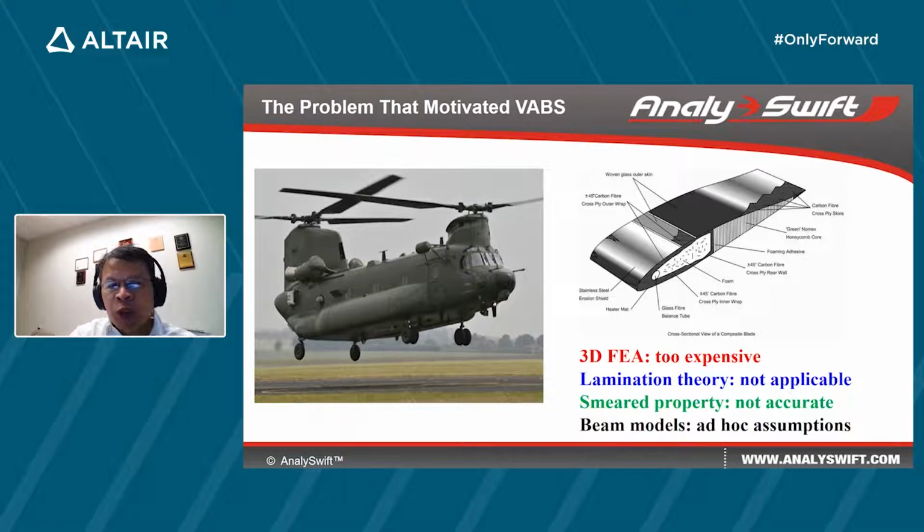Researchers also constructed beam models for rotor blades by introducing a series of ad hoc assumptions to reduce the original 3D problem into a one-dimensional beam problem. Usually, those ad hoc assumptions are valid for isotropic homogeneous beams, but not applicable for composite beams, particularly those featuring significant heterogeneity and geometrical complexity. These assumptions will lose significant accuracy in the prediction.